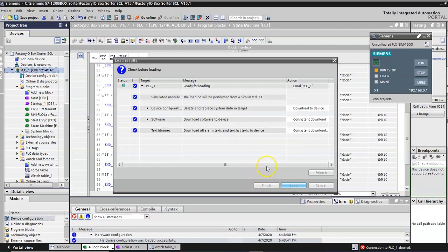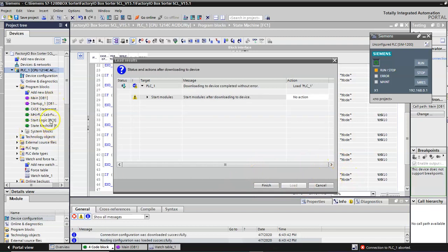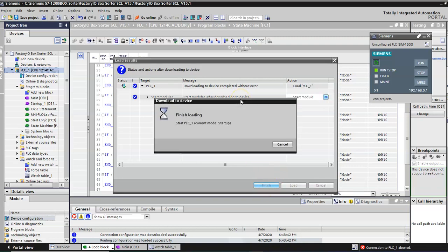And when you do this, like we showed that initial startup logic that we had, you might say, why in the world would you ever write that in structured text? And you wouldn't. You would put it in regular ladder logic, or in a set reset with functional block diagram. You wouldn't want to write it there. That was just showing you what it looks like, because it does look a lot different than everything else.